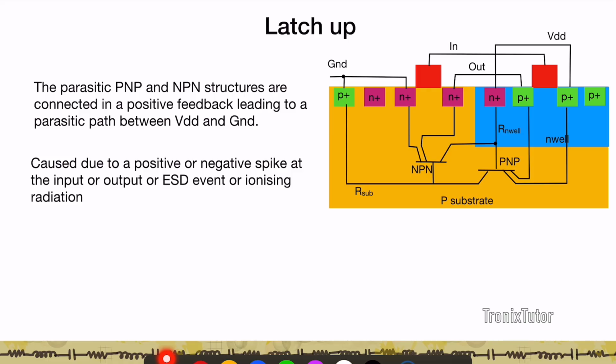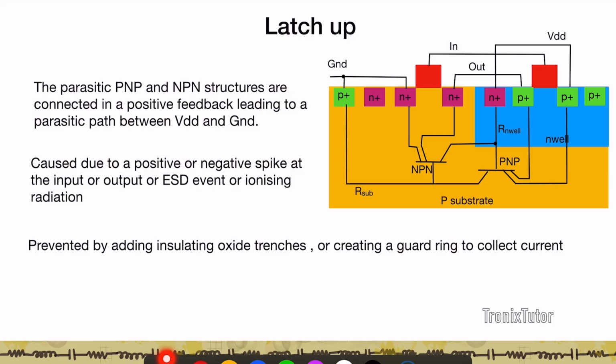And so there are specific rules available for latch up, and those would include adding some trenches in between or creating what are known as guard rings, especially when you have the possibility of a large voltage difference between two wells, if you will.